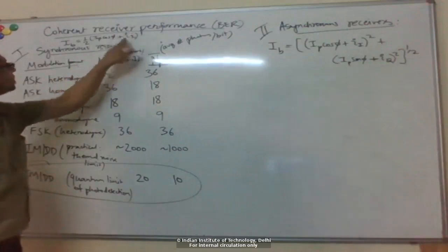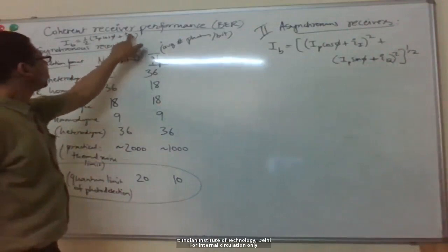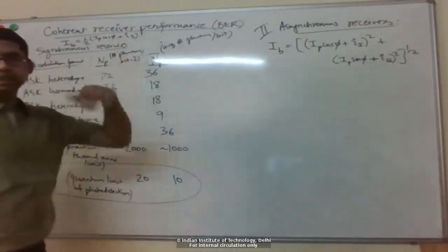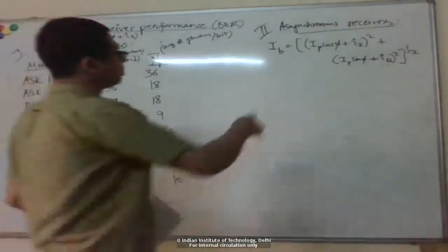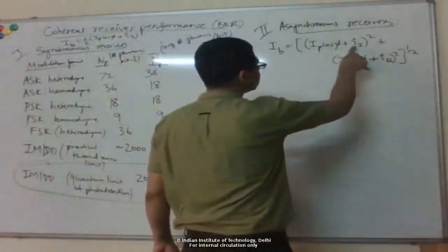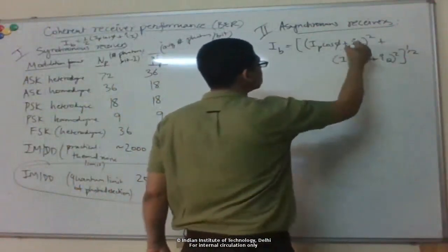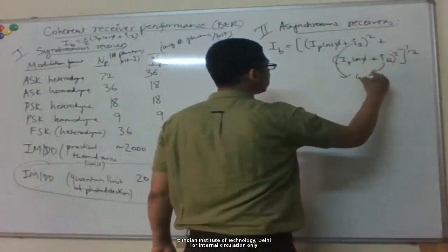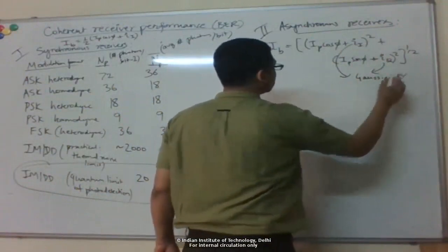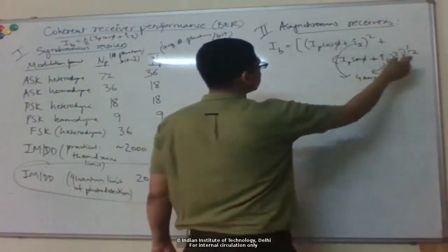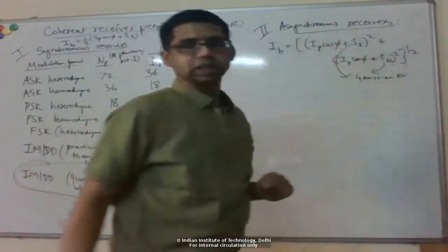So this is like an additive noise, so it's easy to model, and if we take a Gaussian random variable here, then the analysis is similar to what we did for the IMDD. But here, now you can see the noise is adding at 2 different places, and we are taking square and square root also. So if you take Gaussian random variables for the in-phase and quadrature phase noise currents, then the total noise current for this baseband current will not be Gaussian.